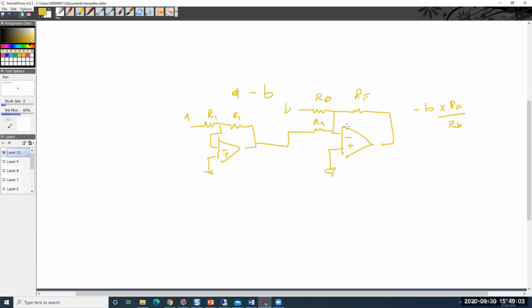Okay. All right, so now this would be minus A R2 over R1 times minus RF over RA. The minus signs cancel out, and then I can independently set that. So the problem is that if everything was subtraction, then that'd be fine. But when you're mixing it up, all of a sudden I have that extra part. And that extra part, just to do an inversion, takes up a lot of board space.